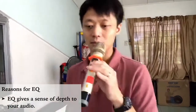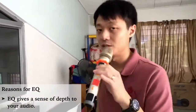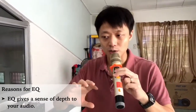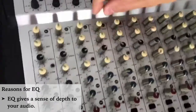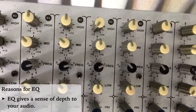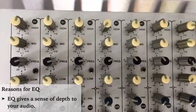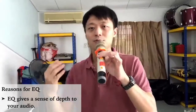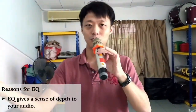EQ is also used for another purpose. I'll give you an example. You have a lead singer standing in front and he's singing, and then you have some backup singers singing behind. You can actually EQ their voices to be lower a bit so that they sound further away from you. For example, I turn down the high frequency all the way down to 15. Now you actually feel that this guy here speaking is further away from you. You can set this kind of setting for the backup singers, so the audience will feel that they are behind. They are not so obvious in the whole mix of your sound.